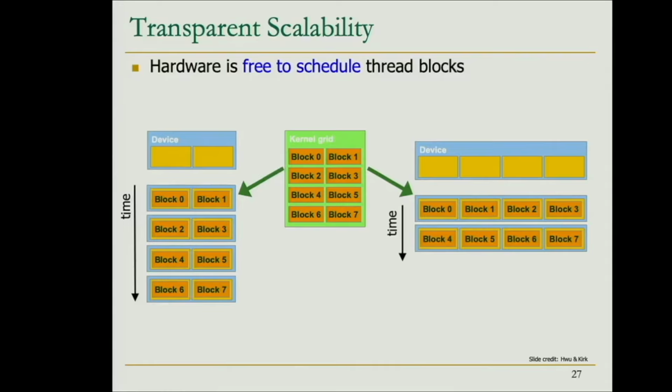So if we want to make sure that these 8 blocks have finished, the only way of doing this is terminating the kernel and then launching a new kernel. So if eventually we need threads in this block to use intermediate data produced by threads in this block, we will have to terminate the kernel and launch a new kernel with maybe, again, 8 new blocks.